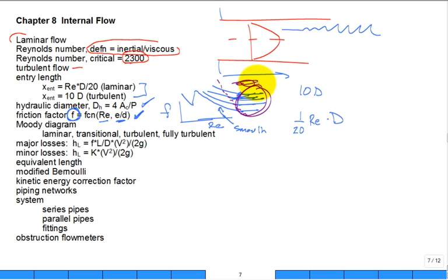We do spend a lot of time in applications where it's turbulent flow, but not so extremely turbulent, and the pipes are relatively smooth. Why have a lot of rough pipes? I mean, you eventually have rough pipes due to junk depositing on the walls in them, but in a brand new pipe system, we don't purposely put in rough pipes to increase the pressure drop. And a lot of copper tubing, very smooth. PVC, very smooth.